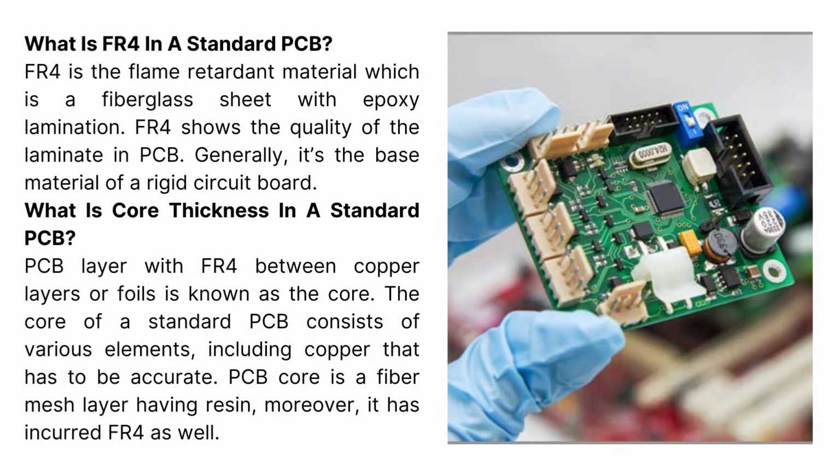What is FR4 in a standard PCB? FR4 is the flame retardant material, which is a fiberglass sheet with epoxy lamination. FR4 shows the quality of the laminate in PCB. Generally, it's the base material of a rigid circuit board.